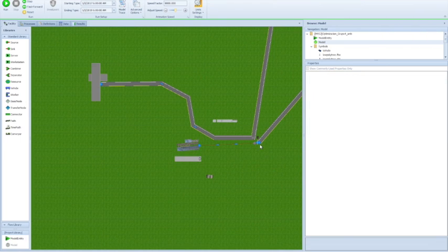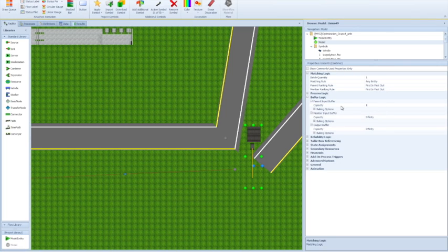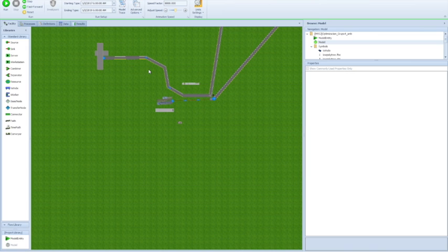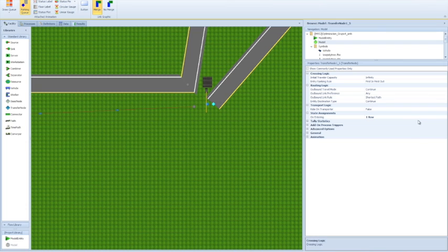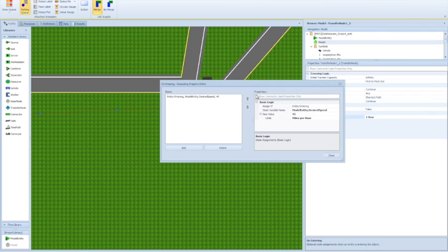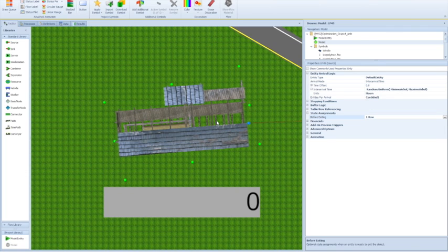Second, for mounting the load of goods onto the transports, in this case the trucks, we have a combiner. In this combiner, we have a capacity of 1, just for one load of wood, allowing it into one truck. For the speed, we have a transfer node. In this transfer node, we change our state variable, in this case desired speed, to 45, which is the maximum speed that the truck will hit when it's loaded. Last but not least, we have our source where we create our lots of wood.